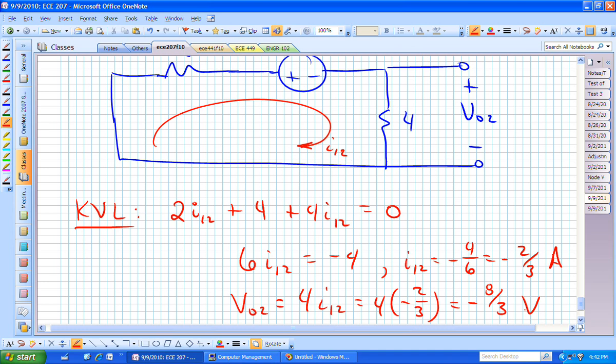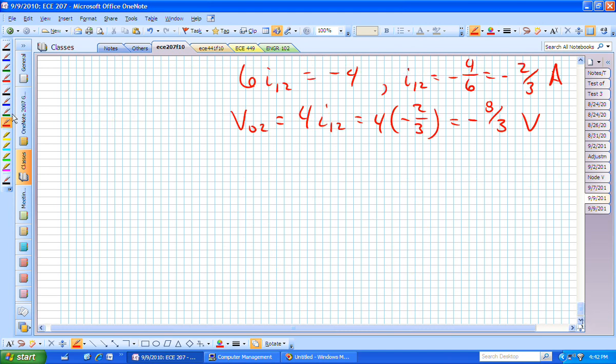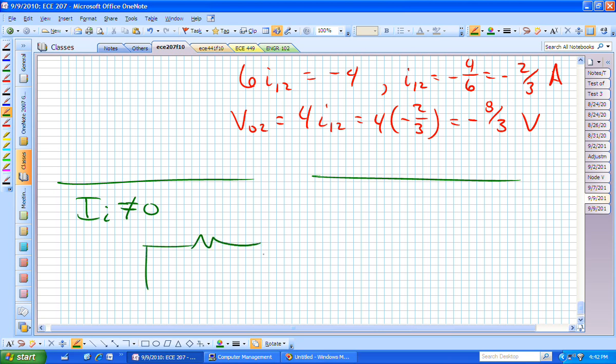That just means for that particular voltage source, it's wanting to make V naught negative. That's fine. That's just the way that source is working. Questions on that? Now we've analyzed it twice. Let's analyze it a third time. And now we want this current source to not be zeroed, but our voltage sources are zeroed. That means those become shorts. Here is I sub I, which is 4 amps.